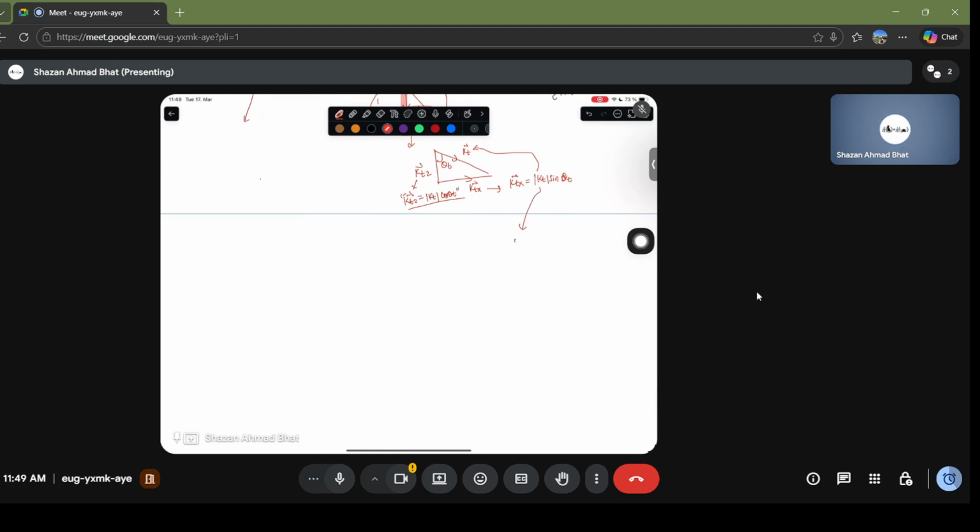The magnitude kt will be equivalent to omega under root of mu epsilon, but this is of the slab because it's inside the slab, the transmitted. It depends upon where the transmitted wave is. If it's in the air, then you use the values of the air. If it's inside the slab, then you have to use the values of the slab itself.